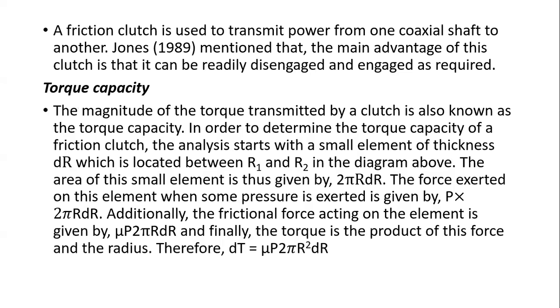So here, what we normally do is that we want to transmit motion from one rotating member to the other one stationary, without first of all stopping the rotating member. We want that motion to continue and be stepped. So what comes in between is a mechanism. Our mechanism is a clutch. In this case, we are particularly referring to one which relies on friction, hence a friction clutch.